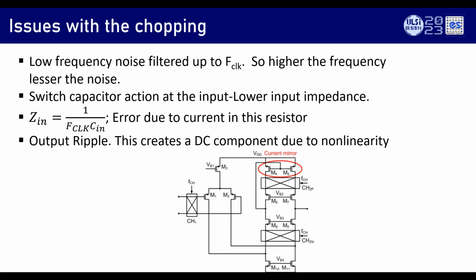Jitter. If you take the average jitter to be 0, then it should not matter. But if you have a skew, let's say that the chopping relies on a 50% cycle, right? Now instead of 50, you have 49 and 51, then you'll have a residual ripple. You'll have something to that.